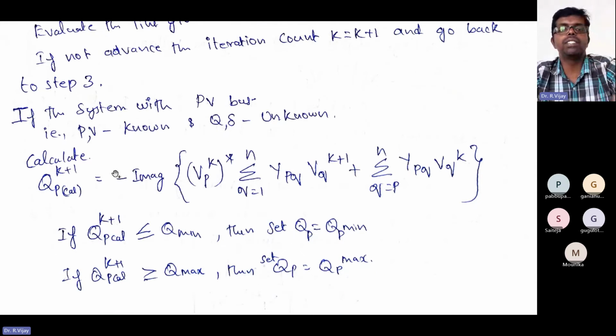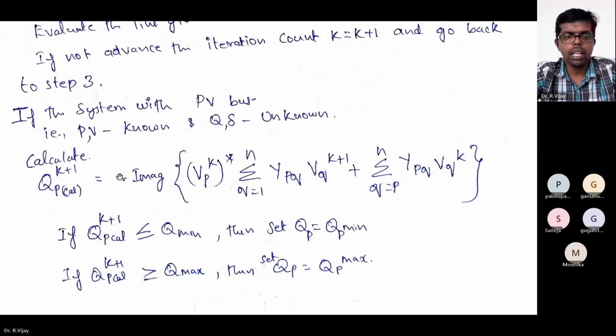Okay, previously you have seen the real power, that is PP calculated. Now we are going to calculate the QP calculated. Okay, reactive power calculation also we need to do. So it is the minus imaginary of this formula.